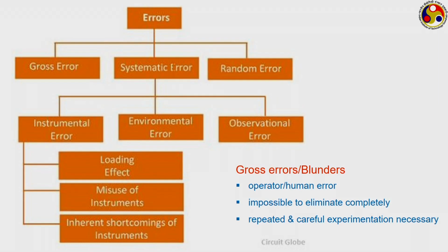Environmental errors are related to different environmental factors. If there is some kind of measuring instrument which is open to the surrounding, then it can be subjected to all the heat interactions with the surrounding air, the flow of wind, dust particles, etc., which can change the sensitivity of the instrument or may lead to zero drift or sensitivity drift, which we refer to as environmental error.